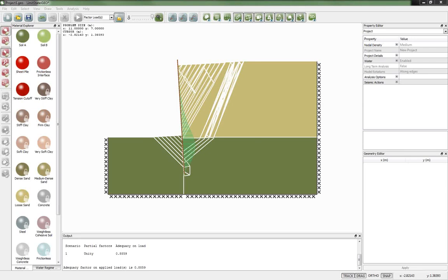So another question relating to piles. So piles in clays, or large diameter piles in clays. Effectively, as I've just said, you can represent those using the soil flow model, but it's up to you to decide that that's the right idealization, and you have to enter the force required for soil to flow around a pile.